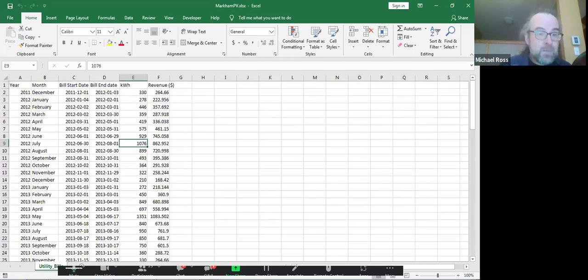So why is it not easy to detect faults here, other than that one extreme fault? Well, 2 reasons I would posit. One, you look at the billing date. It changes all over the place. So our billing periods are not all, say, 30 days. Some of them are, say, 28 days. Some of them are over 40 days. So when we see variability in the kilowatt hours produced in the revenue, we have to ask, is that due to variability in the functioning of our system, or is it simply that the billing period is shorter or longer than the previous and the next billing period?